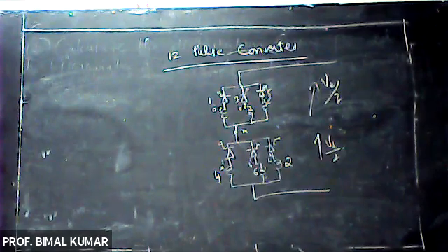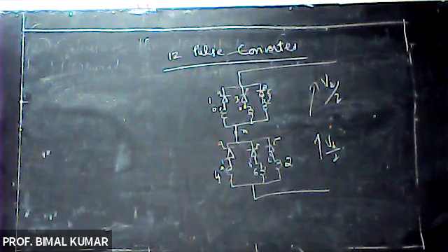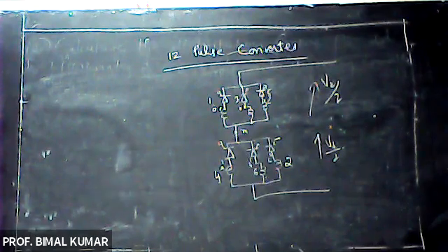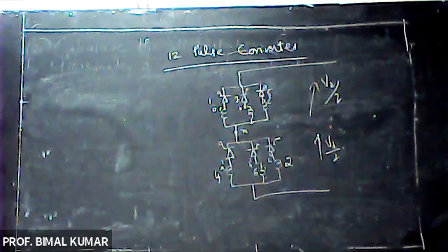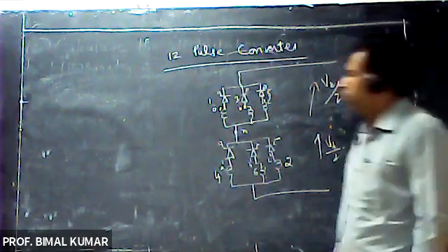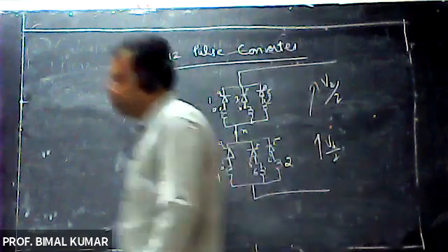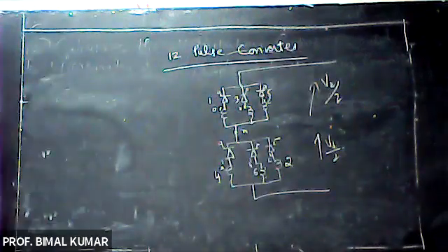In case of a 6 pulse converter, if we are using 2 valve groups that can share a single transformer winding, then transformer utilization can be improved, right? And generally, to improve the output, we will prefer to use a 12 pulse converter.